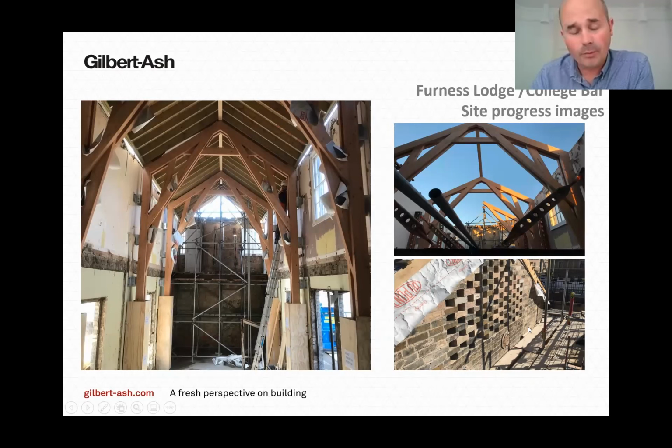Just what Robert was touching on there, just the hit and miss brickwork where you can see on the apex of the gable there, that we introduced hit and miss brickwork there. What was sampled through with Stanton Williams and the client, really to ensure that the brick selection and mortar all matched in with ensure the listed building consent was met and all the applications were discharged appropriately.